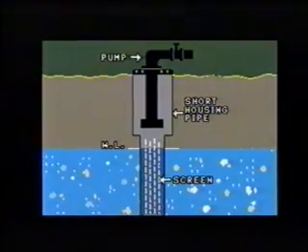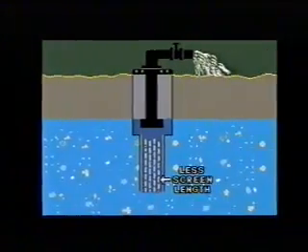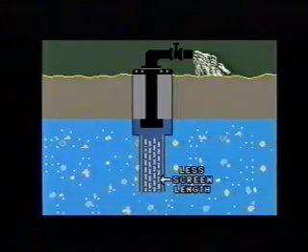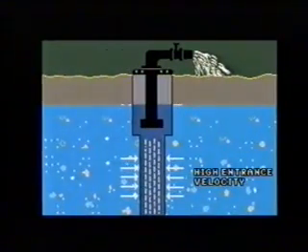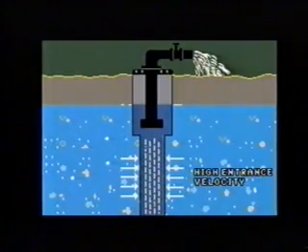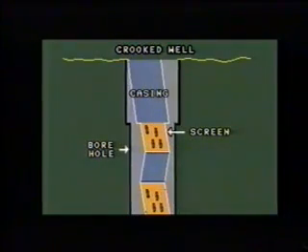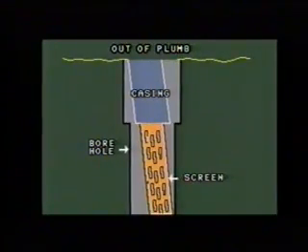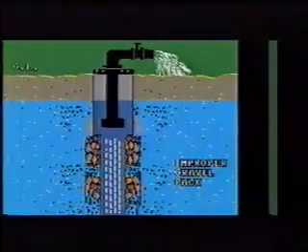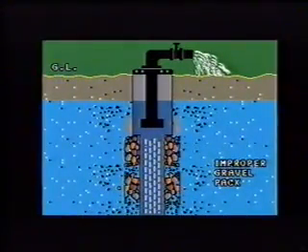Design faults are due to short housing pipe, less screen length, and high entrance velocity, whereas construction faults include crooked well, well out of plumb, and improper graveling.